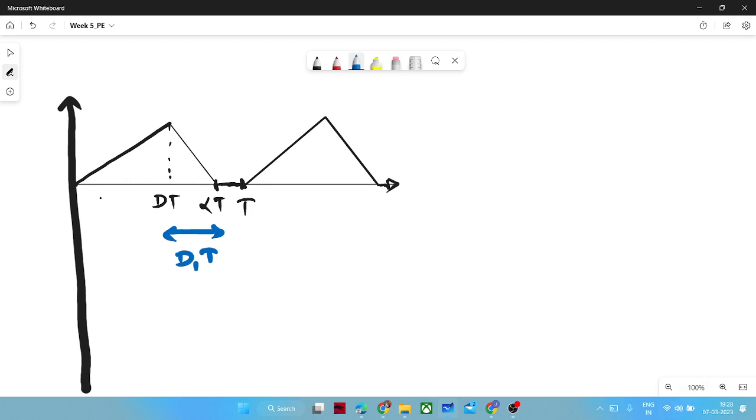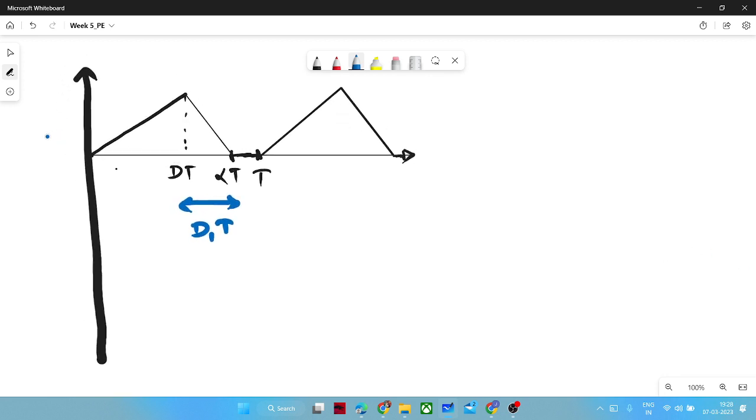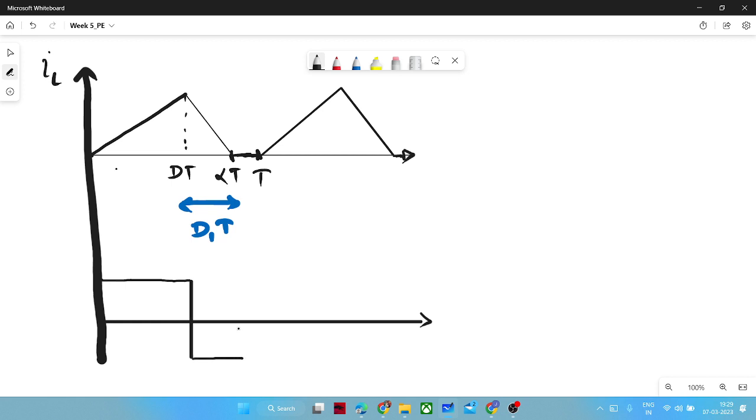Now, if you plot the graph of voltage based on your inductor current, generally we draw voltage only, but since we are defining the discontinuity in terms of inductor current, we will see it. When the inductor was charging, our circuit was having the voltage of V in minus V naught, and when the inductor was discharging, minus V naught, and it will remain zero for a certain period.